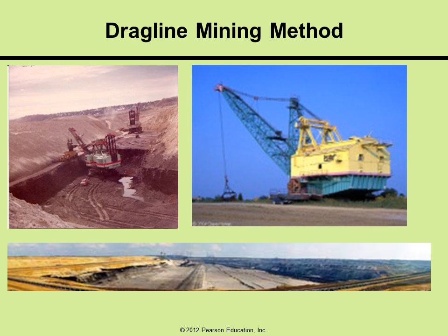In dragline mining, what we use is a great big dragline machine, and it drags a bucket along the overburden or through the ore to collect the load and transfer it to a haul truck for transportation to the processing center. These draglines are huge, and here we see a normal sized vehicle, a car, right next to a dragline to help you get a sense of the scale. If you send the dragline to remove the overburden, the stuff you don't want, first, you might then have a second pass, and that's what you see going on here in the bottom, where the overburden has been removed off the left, and then progressing to the right, you'll see the ore has been progressively removed and hauled away for mining and used as a commodity.